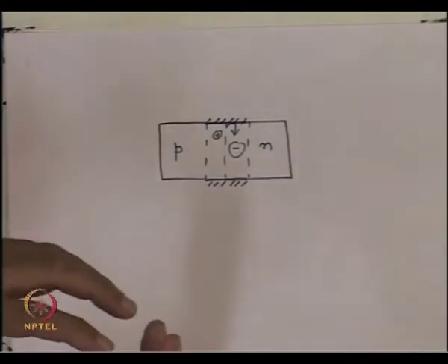So, in fact, by making the fabrication of LED in such a way that I have some kind of reflecting boundaries which will make the photons confined for a longer time inside the depletion region, the same LED can be converted into a laser. So, in principle, a forward bias PN junction made of a direct band gap material with proper polishing of the surfaces so that the photons can be trapped will act like a laser.